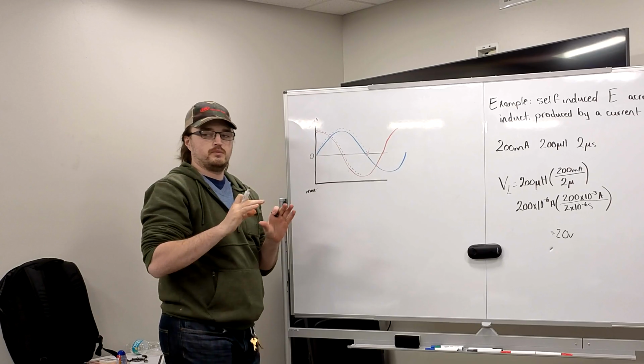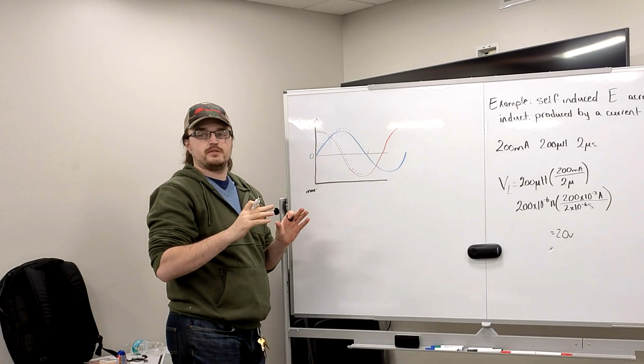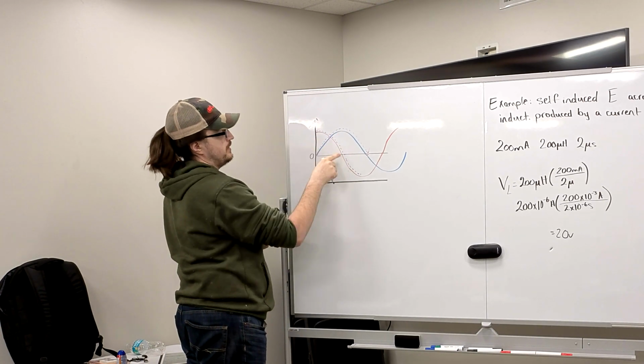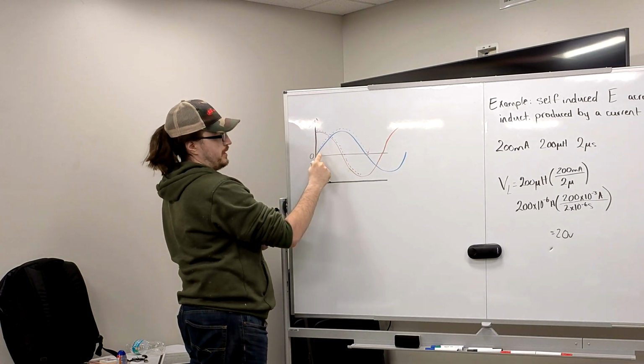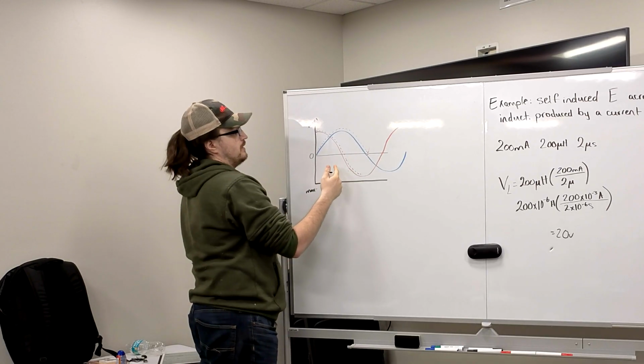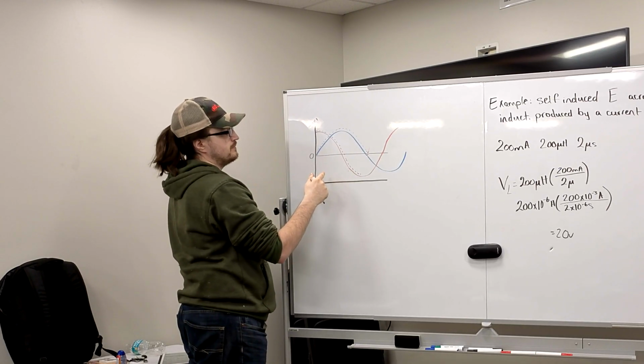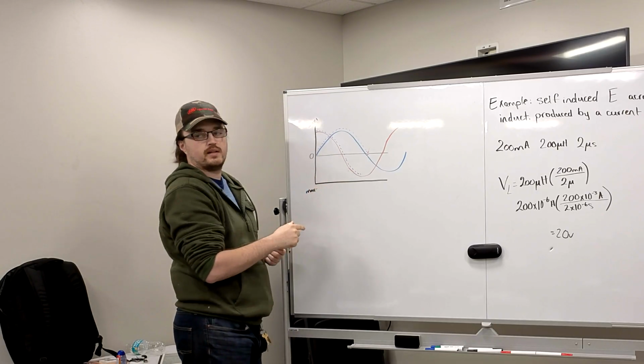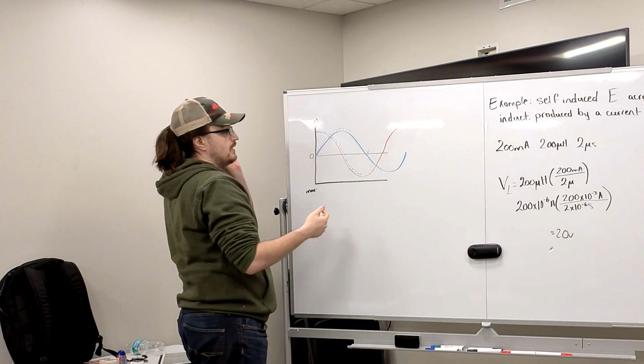Because now, remember, what decides is the direction of change. So this was going in the negative. This is going down, which is why the amperage is going up. So are they in phase or not in phase? They're not in phase. No, they're 90 degrees off phase.